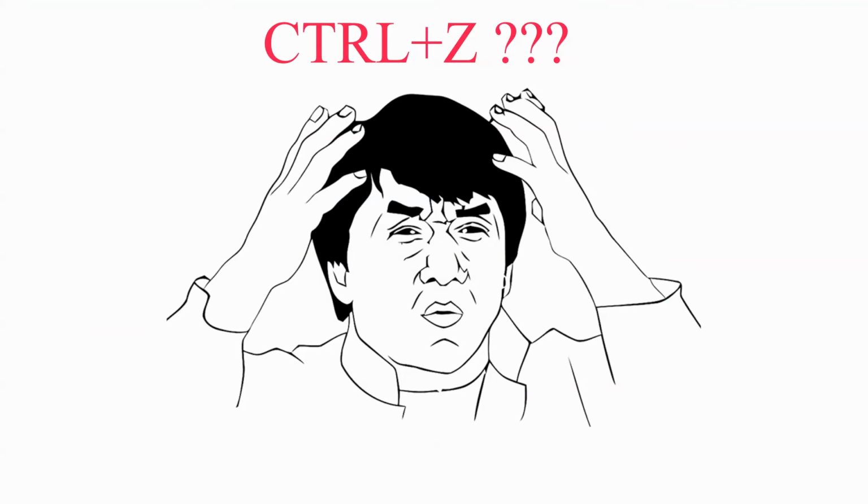You may have noticed that instead of standard CTRL Z, we had to use the delete command. In ANSYS, you cannot go one step back. There is no CTRL Z command here. That's the first reason why we use an APDL file. It serves as a backup.